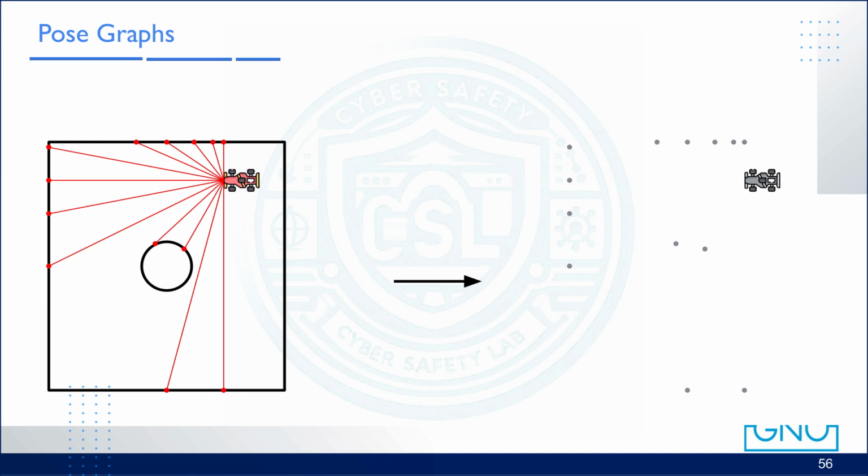If you look at the right side of the figure, you will see a chain of gray and blue car icons accumulating as the robot moves. Those icons are the nodes, and the conceptual links between them represent the edge constraints. So in summary, nodes contain the estimated pose and its scan. Edges represent the relative pose constraints obtained from odometry, and as the robot continues moving, the pose graph grows naturally, exactly as shown in the illustration.